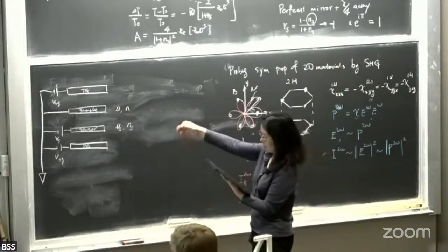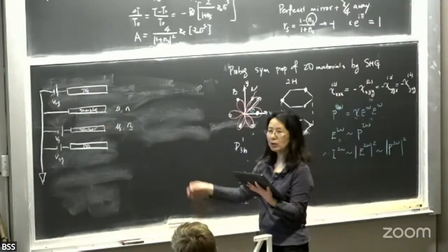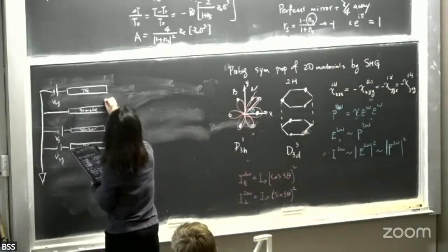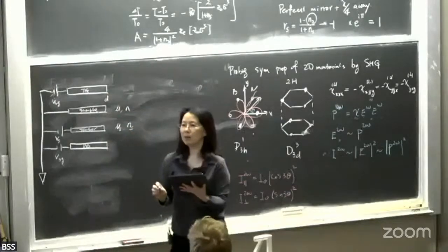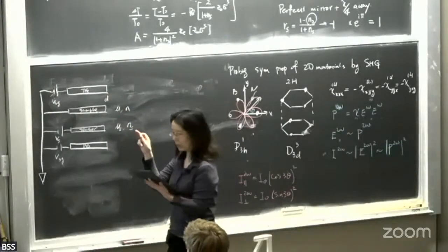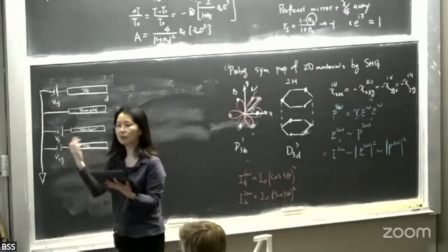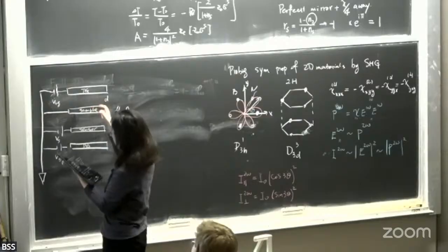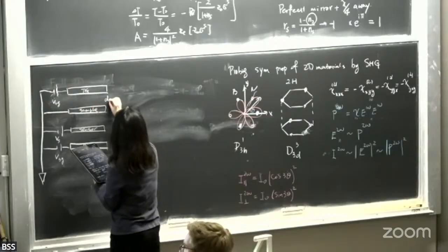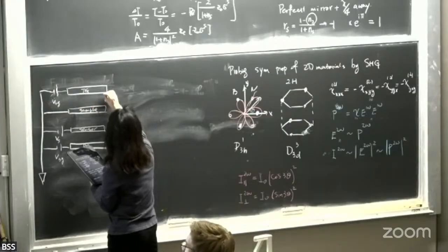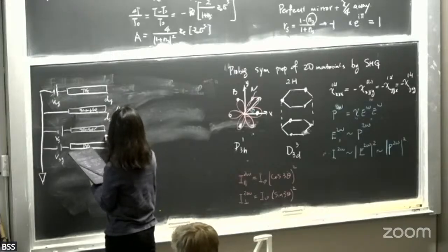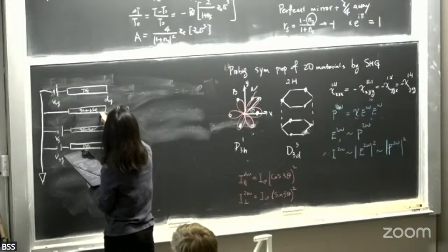This is just parallel plate capacitors in series. If we know the distance between the plates and know the material in the middle, we can compute or even measure the geometrical capacitance for each. So let's call this TDG. That's the distance between the plates, and call this DS. This is the bottom gate. So those are the thicknesses.